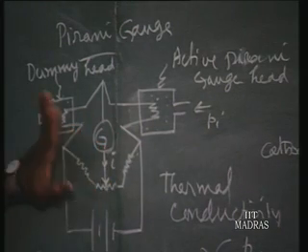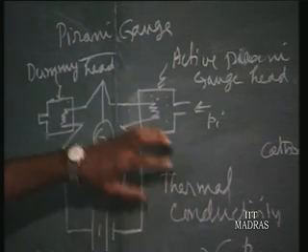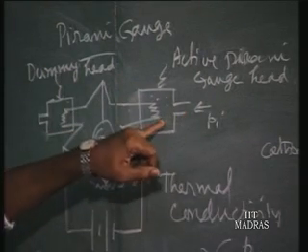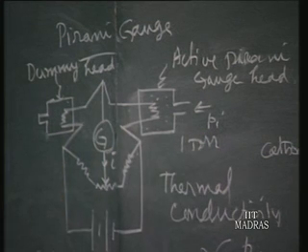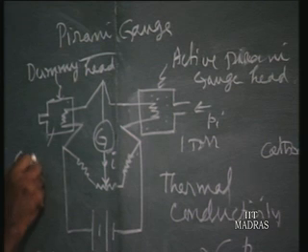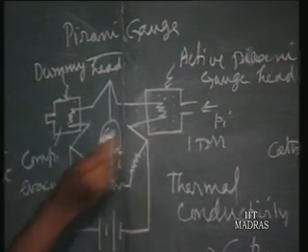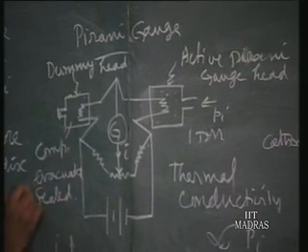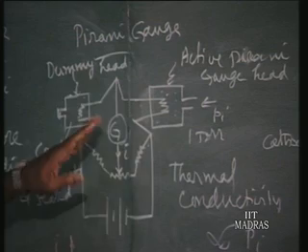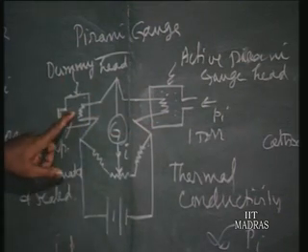So you have to calibrate this. For calibration, we fill this volume with gas at, say, 1 torr, and the adjacent arm is a similar unit, a dummy head, completely evacuated and sealed. You could have a similar resistance, but it is easy to have the dummy head and fix it as the adjacent arm.